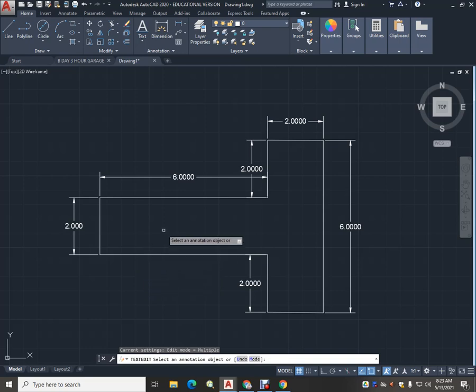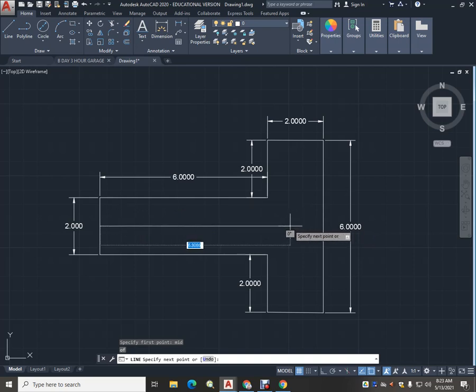So we're going to bring this in down the center. Let's just put a construction line in here, and the construction line has to be right down the center. One of the things we can do with our line command is use a qualifier called MID, and that literally will find the center point or midpoint of the line. I just want to draw a construction line out here, and I'm not too concerned about the distance. I'm just going to put it out here, and I drew that at 0 degrees.